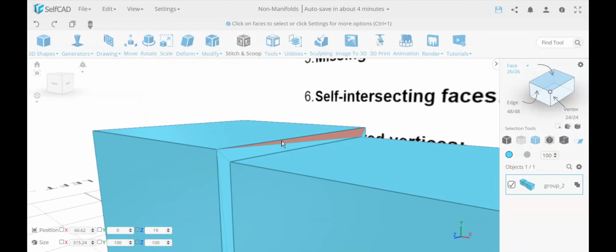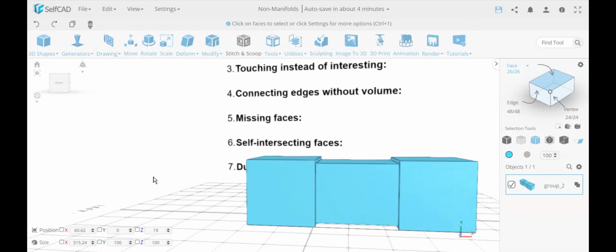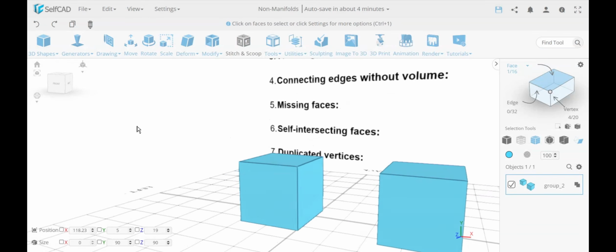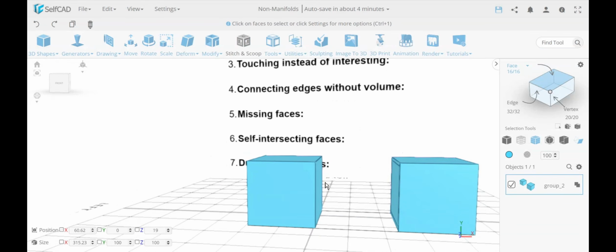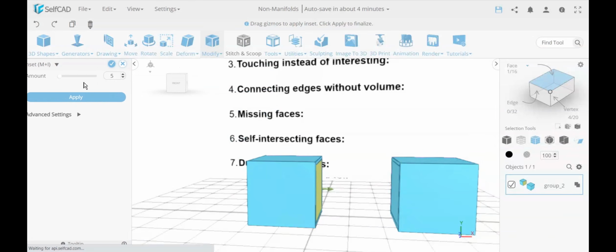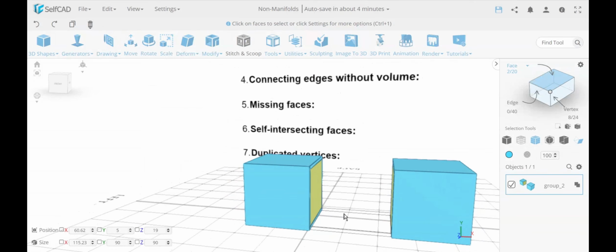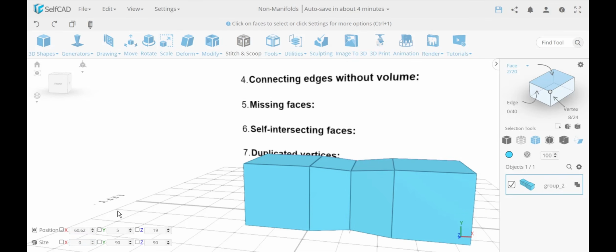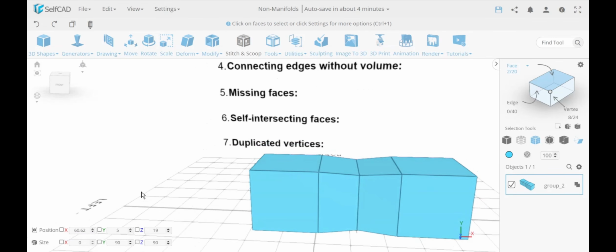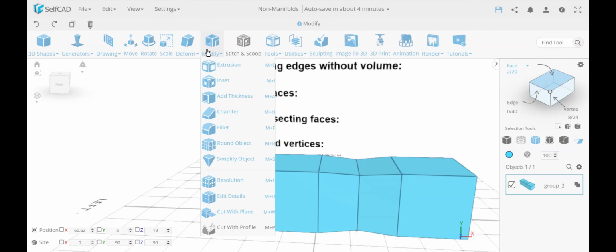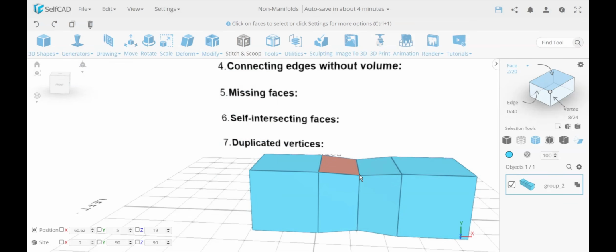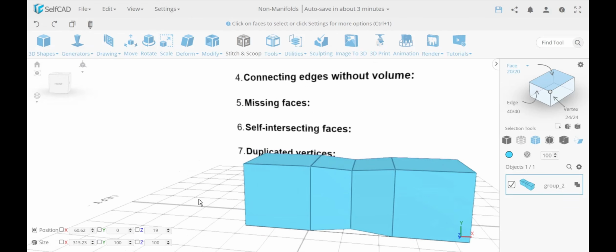You can see over here this is cut, so this is no problem, nothing to remove. But what if I do the same thing on the other side? I select this face and I inset, and now I have these 2 faces over here, and I'm going to make the distance between them in the x direction 0, so they basically come together like this. So this is an example where I actually have 2 faces. I could have used extrusion both to extrude and collapse them at the same time, and because I'm going to both sides, it wouldn't cut. But in this case it's even worse, because it did not remove anything.